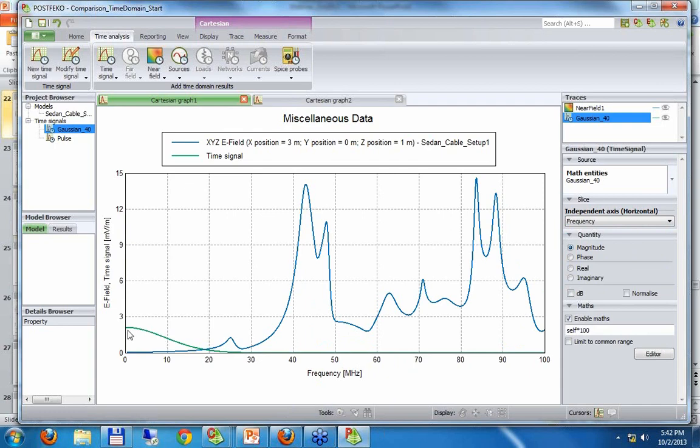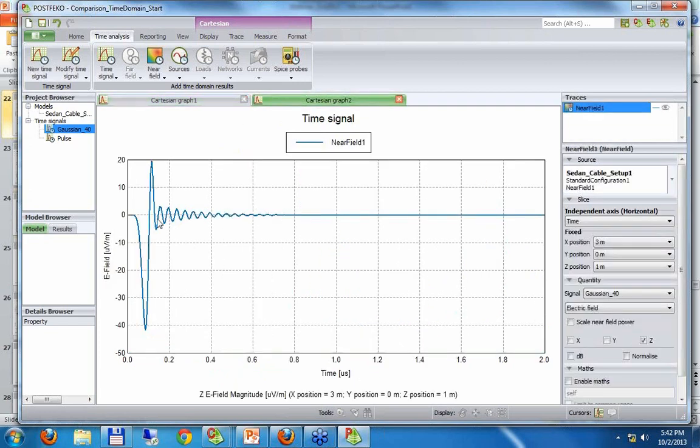You will basically see the spectrum overlapping here, or having spectral content in the lower frequency range. And from this we will still have the resonance here at 25 megahertz filtered into the spectrum. So what we will see when we look at the time domain is a pulse period of 1/25 megahertz, which is 0.04 microseconds, which matches that single frequency that was filtered out in the results.